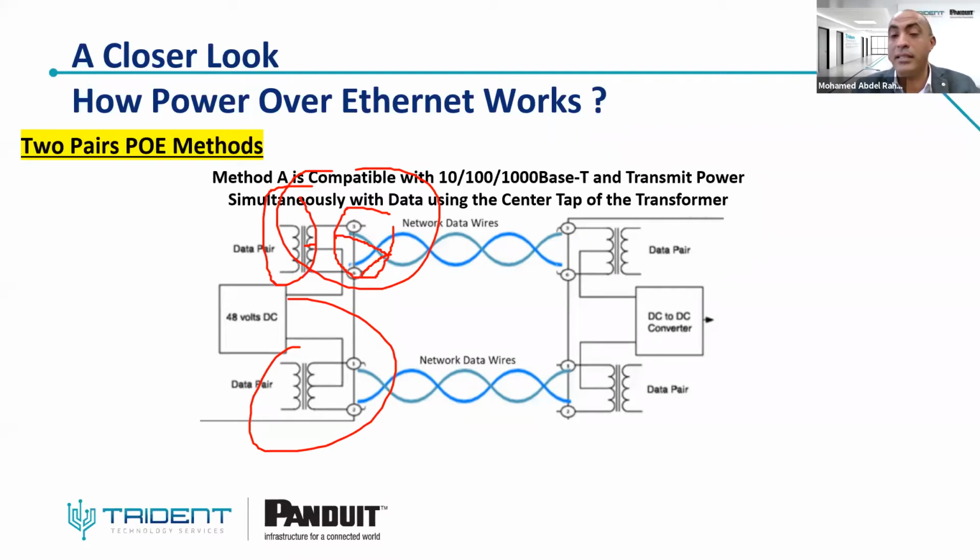We will discuss this point when we talk about testing in an upcoming slide. If you have a mismatch in the resistance between the two conductors, you will have something called DC resistance imbalance. DC resistance imbalance will affect your PoE and can cause distortions for the data signal.